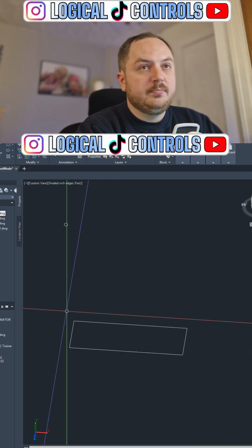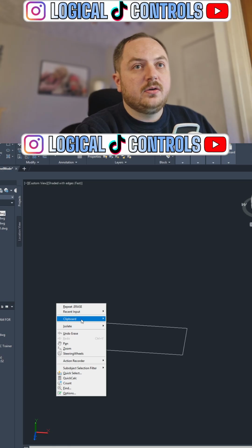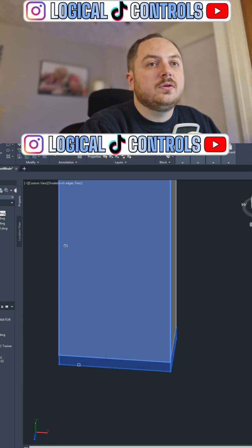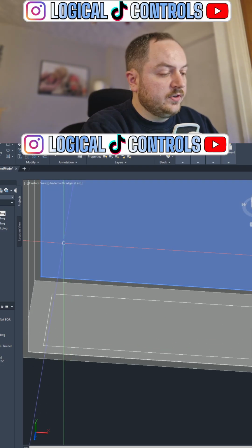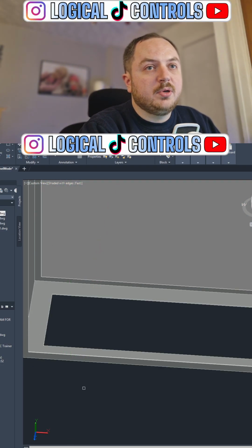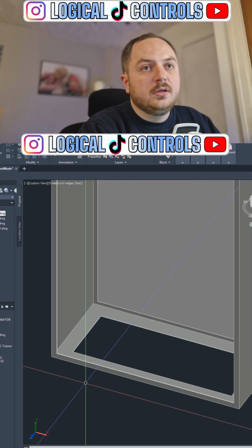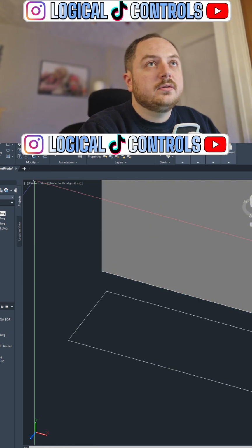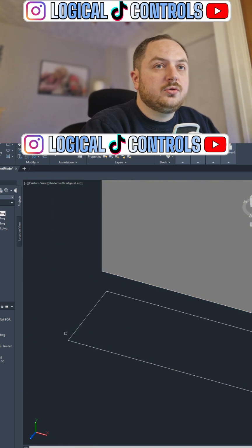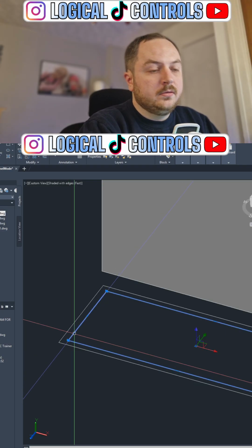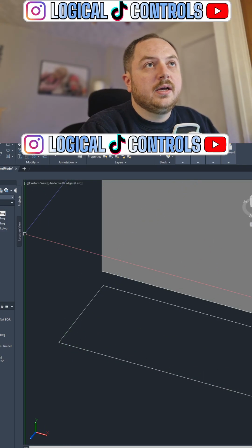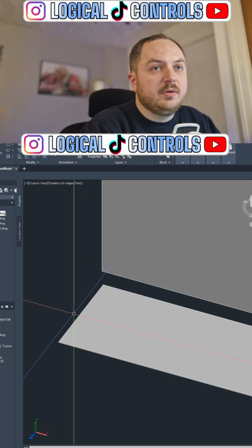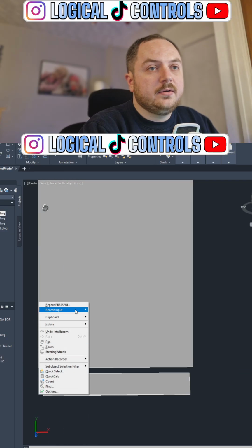Okay, so I can delete that one now. I can delete that off. So we should just be left with the enclosure with a rectangle in the middle. Let's have a look. Yep. So if I do a press pull now, that should just punch straight through. It does. And then using that same rectangle that I had, I can make that 20mm wider, delete the middle one, and press pull that to extrude it and make an aluminium gland plate, which could be 3mm thick.